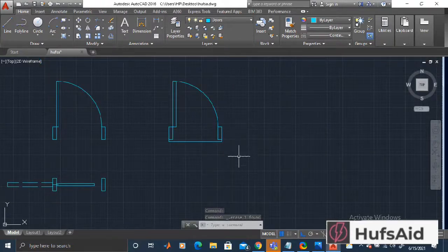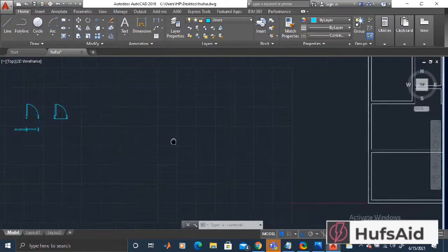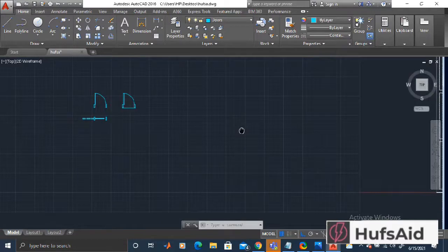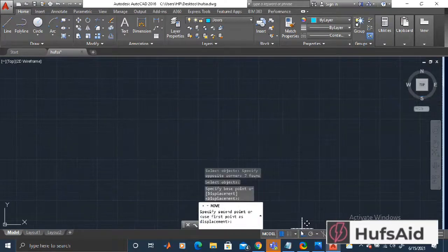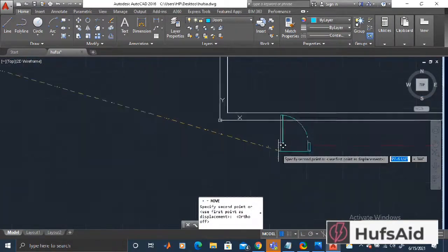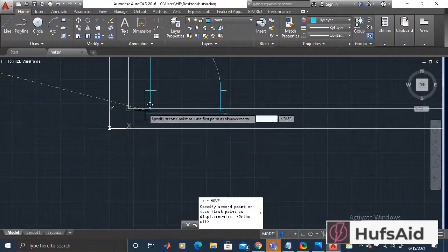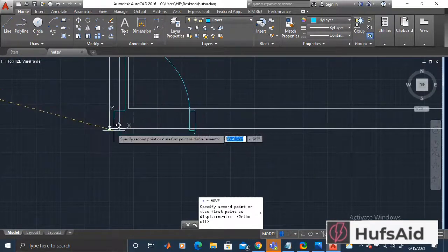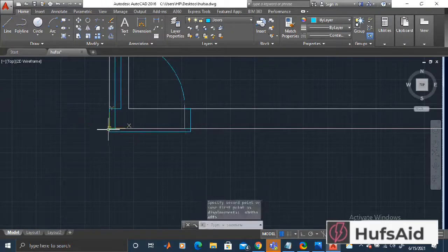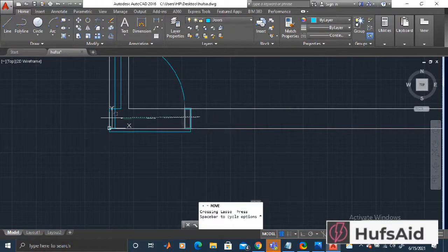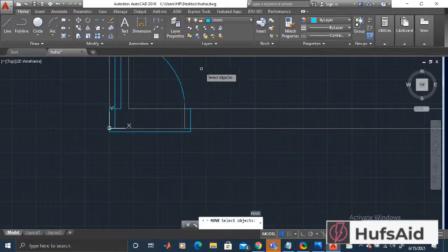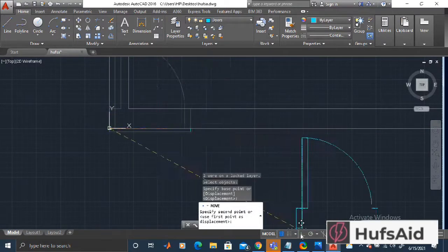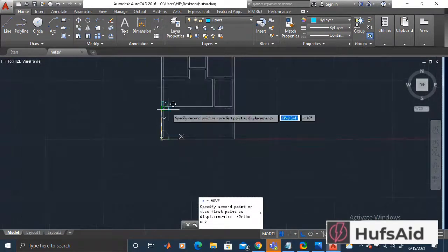We're just going to place the doors in their relative position by just using the rotate command, move command and copy command. So the tip is to pick the door using the object snap and just place the door by joining the corners at your contour, and then you can switch off the object snap and just move it using the ortho mode, so it would move within the contour or within your wall, so it would be fixed and you won't have to worry when you use the hatch command for hatching the walls.